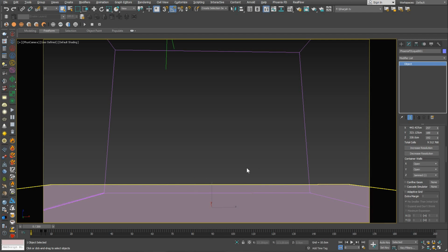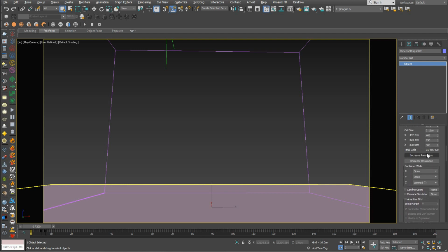Now let's do a good amount of particles, and what we will do is let's change this, let's increase this like 2 times, as an example. 35 millions is a very decent amount of particles, and this is what I expect the final resolution can be. Based on how many particles we will get here, because now we don't know, this is just the cell amount, we will know whether to increase or decrease it a little.